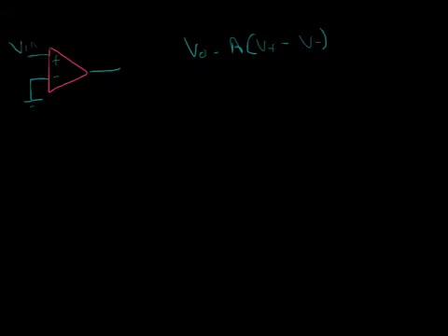Now that we've seen how to pick an op-amp, let's look at how to actually use an op-amp in a circuit. What we've seen till now is that the op-amp gives us an equation like Vout is equal to the gain times (V plus minus V minus). So one could say that I will give the negative input to ground and the positive to Vin. So using this, I should basically get a Vout, which is Vin times the A of the circuit, because V minus is 0.